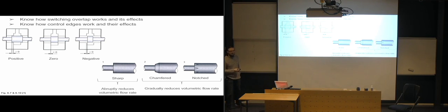The disadvantage is that you can get shocks going through your system, because you are so quickly closing off the flow that the rest of the hydraulic fluid moving towards the valve gets crushed together, almost like a chain collision going on there. So you get a shock moving through your system.